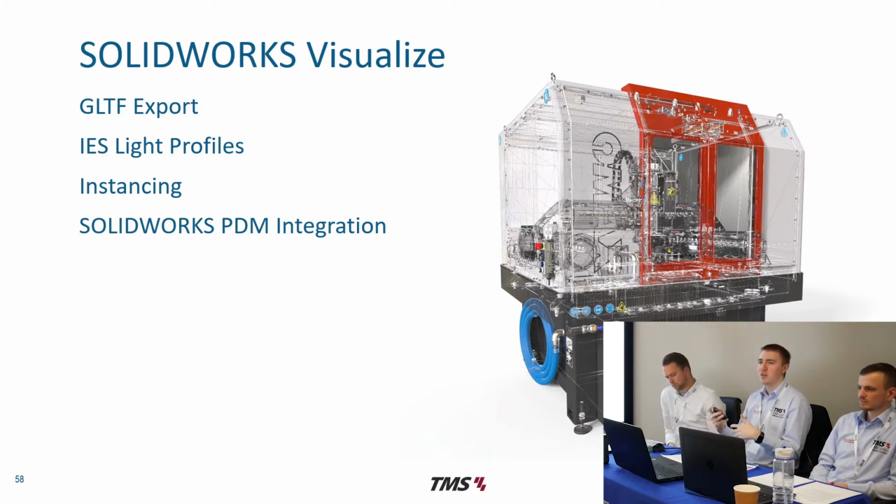Something to where, if you're familiar with things like ray tracing with modern graphics cards, you'll know that you want to try and get the most realistic lighting possible to mimic real world conditions. Also, if we have instancing in Visualize, so that's where maybe we've got a lot of component patterns, circular patterns, linear patterns, whatever it may be, we've got multiple of the same component over and over again. We don't have to render every single one of them out completely from scratch. You can almost reuse some of those renders a little bit, just to speed up the rendering times and reduce the load on either your CPU or graphics card, whichever you're using for rendering.